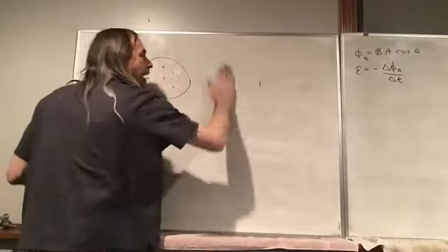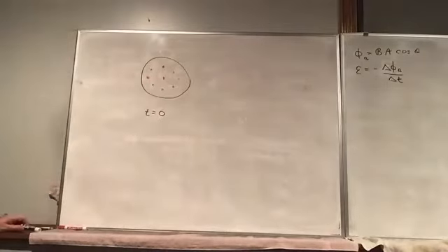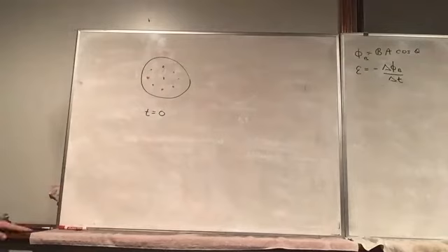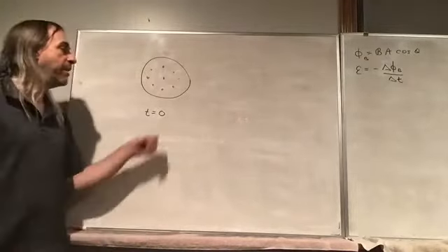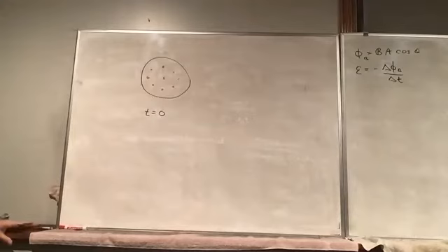So again, if you have a constant magnetic field, if you were to rotate this loop, that would create a changing flux. That's a very important example of flux because that's how we produce most of our energy. So you mechanically rotate this coil, and that'll create an EMF, which will drive a current. So this is kind of the opposite of the electric motor, where you're using a current to cause a rotation. In this case, you're using a rotation to create a current. So kind of the opposite of the electric motor here.